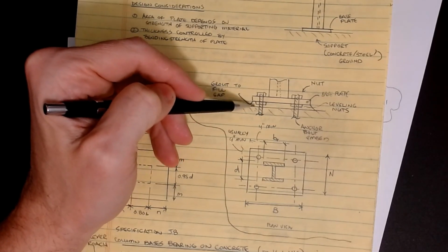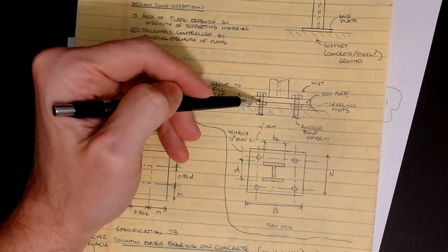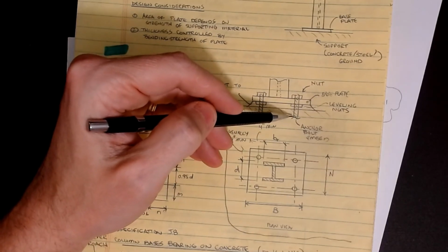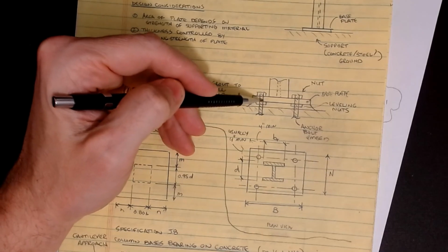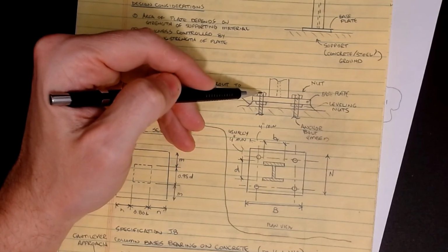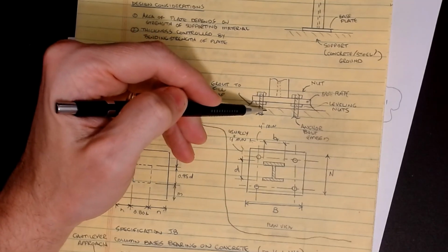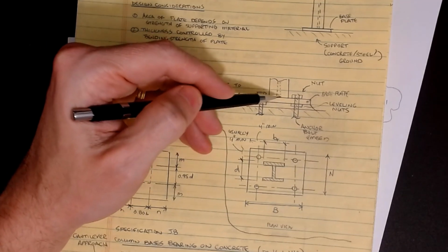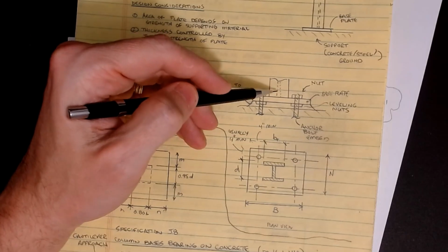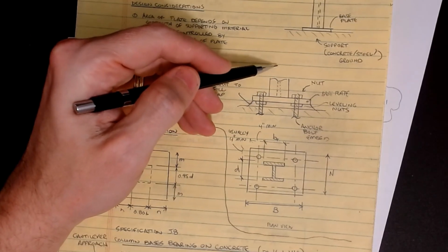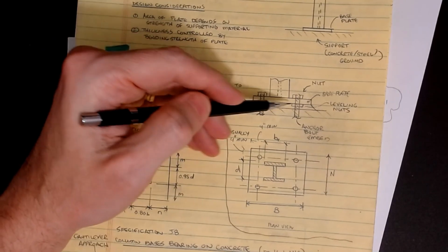There's actually a little bit of a gap in between. And so if this is my anchor rod that's coming up out of the foundation, and then there are holes in the plate where this passes through, normally you think of this as, well, I'm just going to put a nut on this rod and hold this thing down on the foundation and we're good to go. But if this thing isn't square, in order to be able to get this column perfectly vertical, we don't really care what the plate is doing.